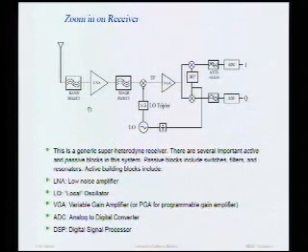One reason is that this receiver, basically using this mixer, first thing it does is it downconverts the spectrum down to a fixed IF frequency. IF stands for intermediate frequency. And we basically do some signal processing at the IF frequency, and we then digitize the signal. So the ADC here is the analog to digital converter.